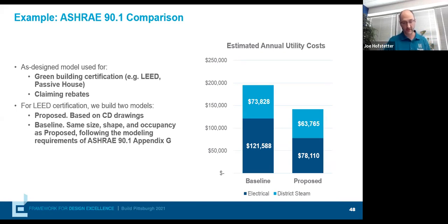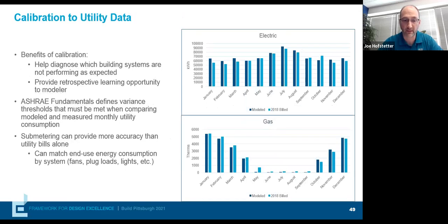But to be mindful of time and wrapping up the last few slides here, the two key things I want to hit on for this later stage part of the process are some more real world examples. One is a project where we had a significant continuous insulation wall system, and by design and by specification, it used more of a plastic or composite clip system that really enhanced the continuousness, if you will, of that insulation.